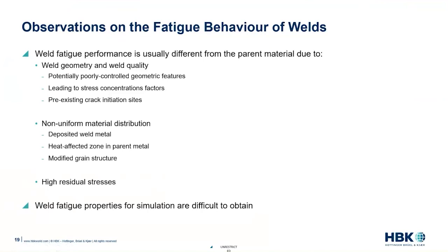In addition, weld fatigue properties for fatigue simulation are difficult to obtain. They are harder to obtain than testing samples of the parent material.